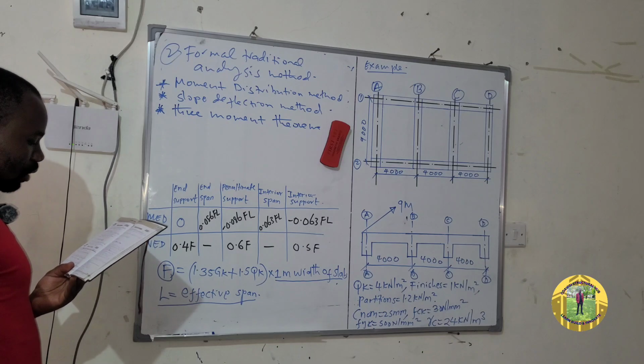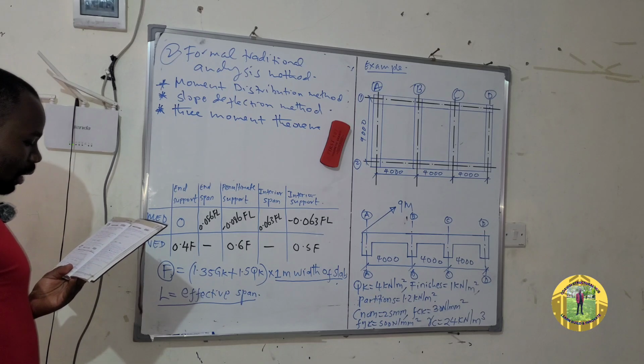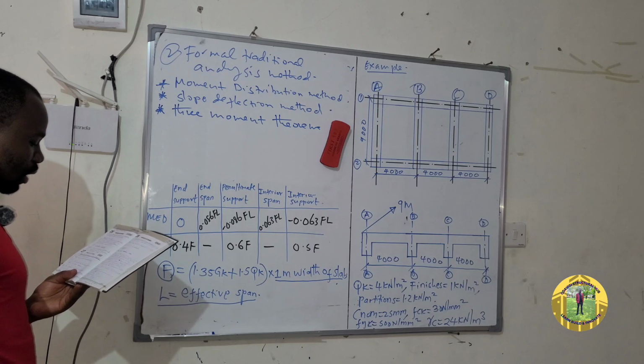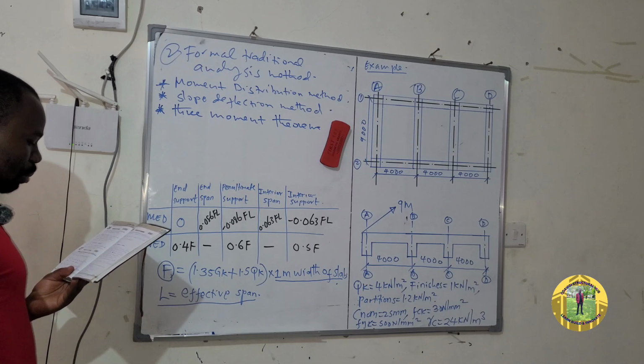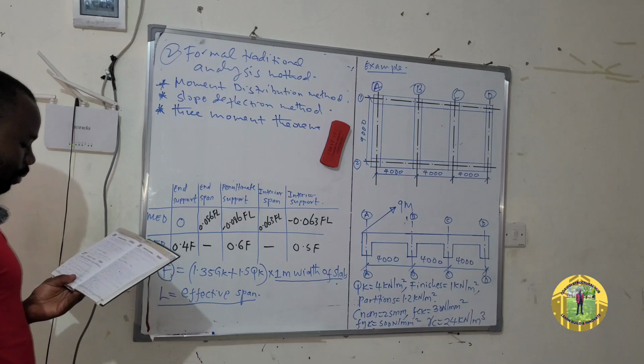You are tasked with designing a slab spanning across 4 parallel beams as shown below on the floor plan. Using Eurocode 2, determine the most suitable effective depth of the slab, overall depth, and hence bending reinforcements. So these are the data.